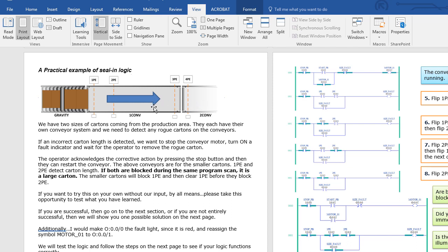Now you know it's leaving and being pulled on because you got both of these energized, because you control them with your logic. So remember, if you've turned on this output to run this motor and you've turned on this output to run this motor, then you know the 2 conveyors are running. And if the 2 photo eyes are blocked at the same time, then either you've got a carton that just broke this one, and somehow there's a different carton, the trailing edge of which is broken this.